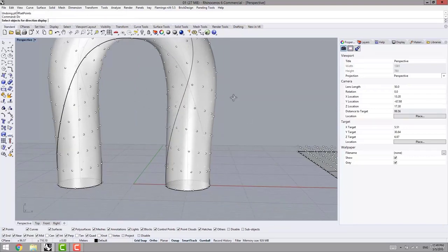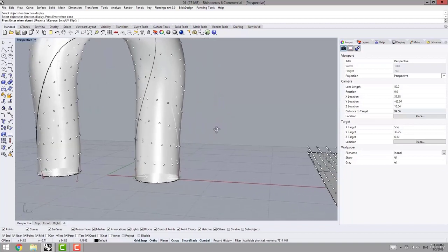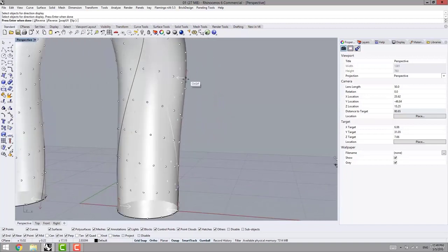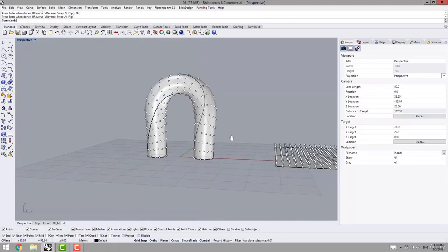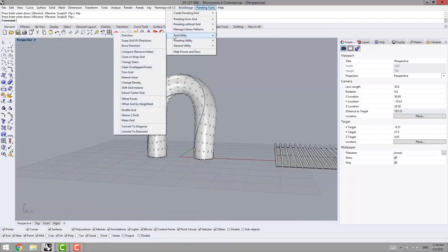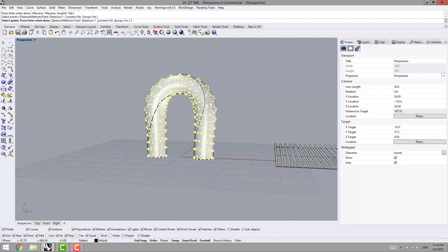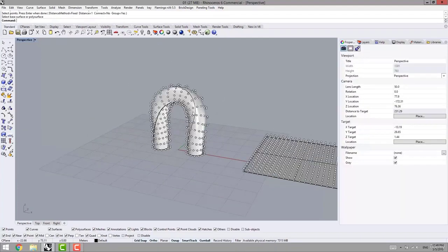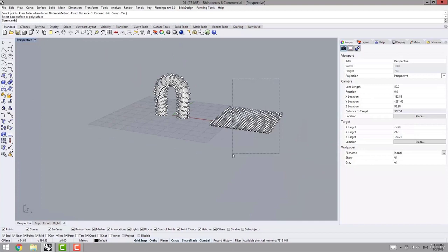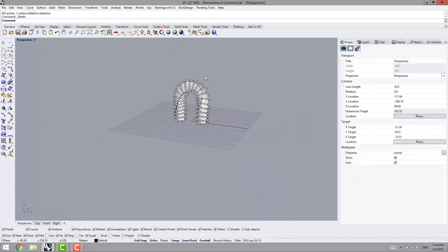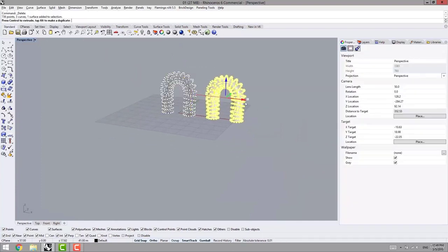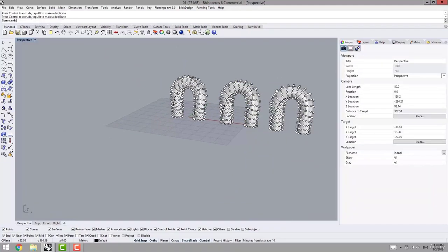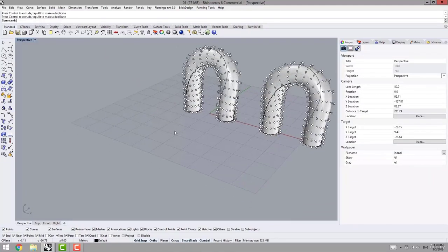The reason is that if I look at the direction of the surface with the dir command, it's toward inside. Now here I can flip to go toward outside, and then I apply offset point, or I could even put minus numbers into distance. Now we have our surface, our paneling grids, and I don't need that. I make 2 copies so we can look at some interesting objects.